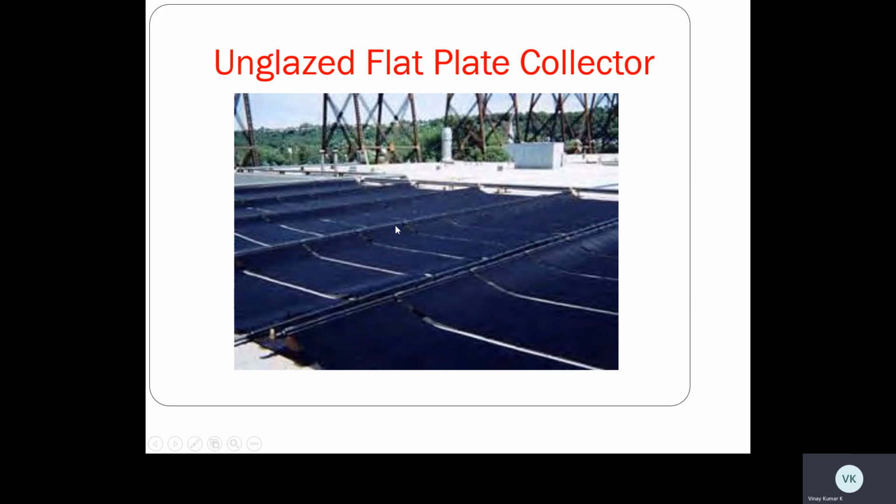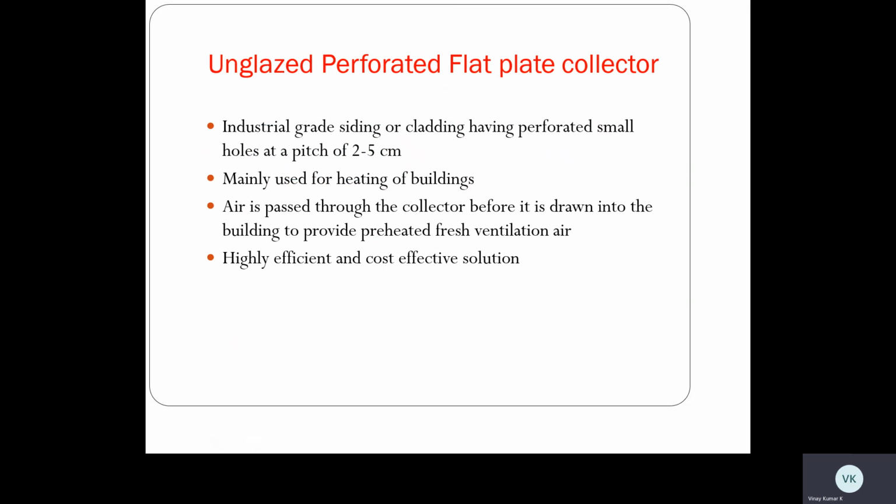The next thing is unglazed perforated plate collectors. So what is meant by unglazed perforated plate collectors? These are industrial grade siding or cladding having small perforated holes at a pitch of 2.5 centimeters, and mainly used for heating of buildings.